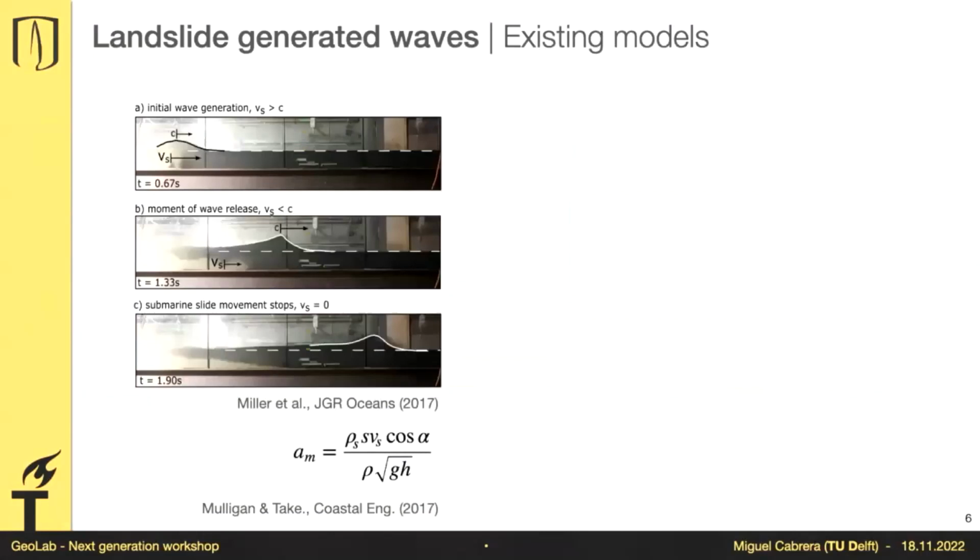Several experiments have been done in the past, for example, these ones that were done in Queens, and they took the Canadian way. They took an ice hockey rink, they put a slope on it, and let a bunch of material fall onto a water reservoir. The impact of that granular flow then generated a wave, and they started to change several aspects. They looked, what if the thickness of the flow is larger? Will I expect to have a larger wave? What happens if I saturate these grains? Will they then displace more water because water will not penetrate into the grains?